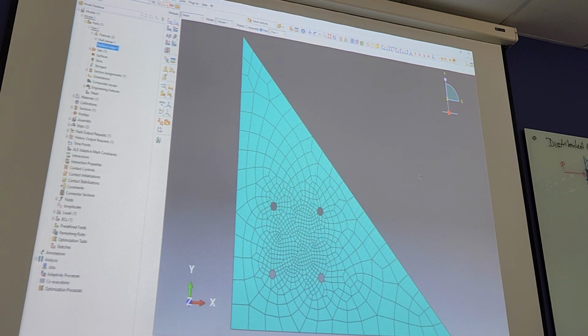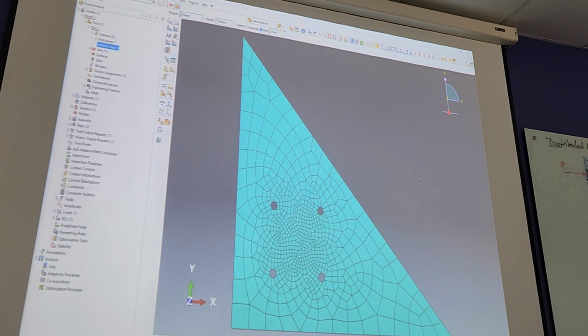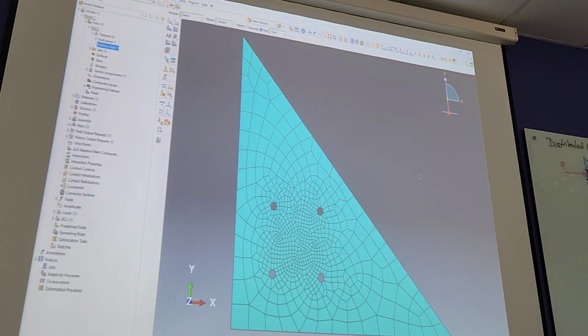The reason is the way elements are defined mathematically. Remember, like we said, spring element, but what Abaqus sees is k, minus k, minus k, k. Same thing here. We see these elements, but Abaqus sees them differently, sees them as equations. The way those equations are defined, they are accurate when it's 1:1. Once they start changing or losing the aspect ratio, their accuracy decreases. That may not be significant, but it does decrease.